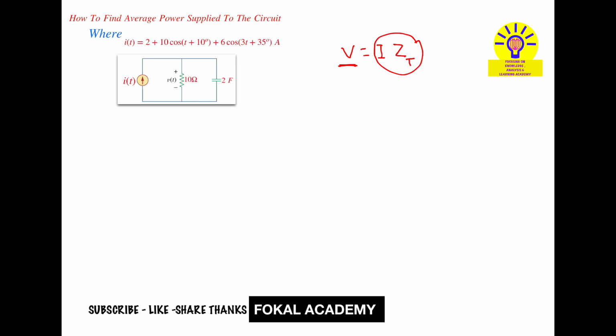So first of all, find the impedance of the circuit. Here a resistor and capacitor are there. The resistor impedance is 10 ohms only, and for the capacitor the impedance is 1 by SC. Here C is 2 farads, so 1 by SC is 1 by 2S, the impedance of the capacitor. So 10 ohms is the impedance of the resistor. Let this be Z1 and this be Z2.